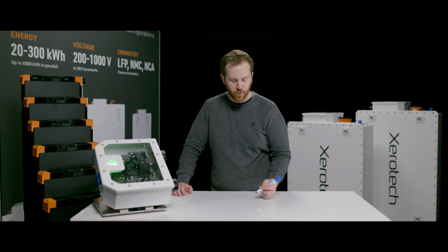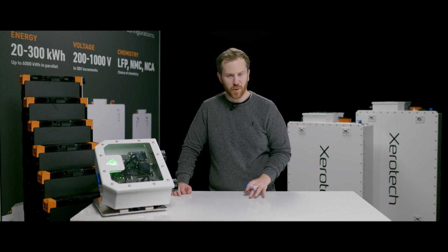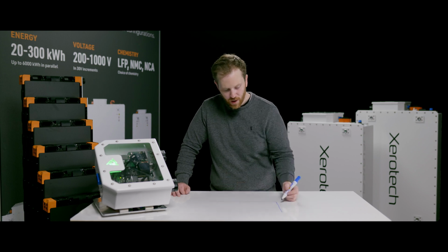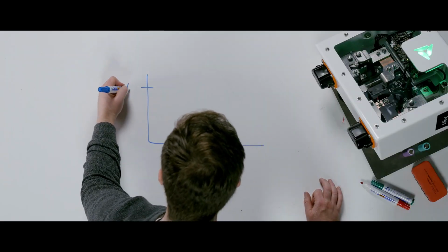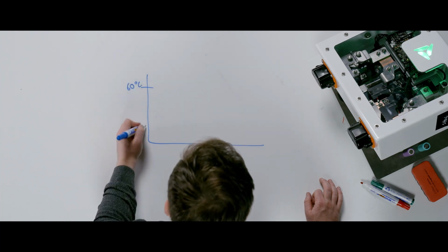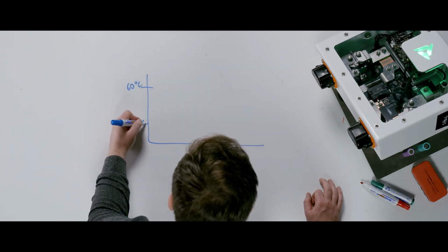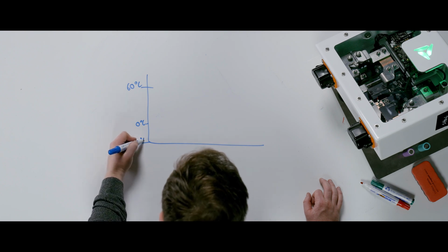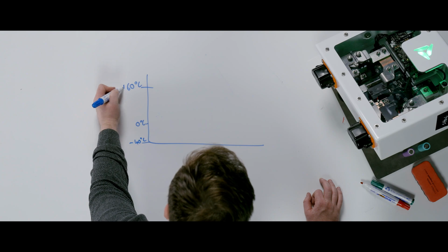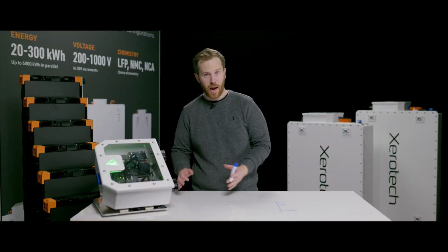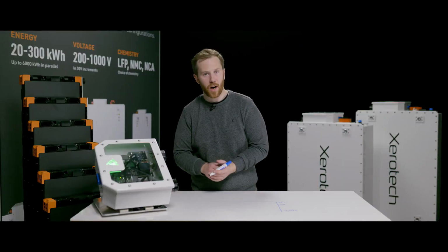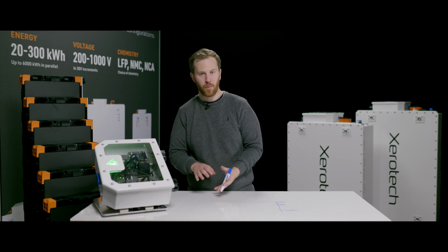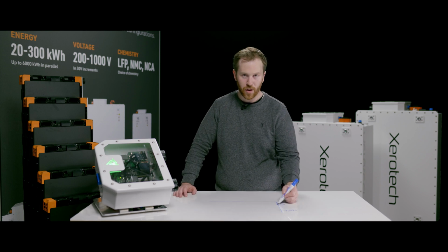One final point that's incredibly important for batteries, particularly lithium ion batteries, most battery cells do not want to operate above 60 degrees Celsius or below 0 degrees Celsius. So when you go below 0 degrees Celsius for a battery, you're able to discharge it at a much lower rate, but you can't charge it. So you basically can't charge most conventional chemistries available on the market below 0 today.